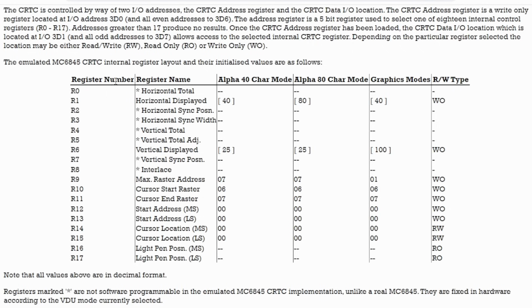And on the Amstrad though, these port addresses are repeated multiple times for reasons I don't really understand. So it still covers 3D4 and 3D5, but if I want to change the register number, I have the option of writing to 3D0, 2, 4 or 6, and similarly odd values in between for setting the values.